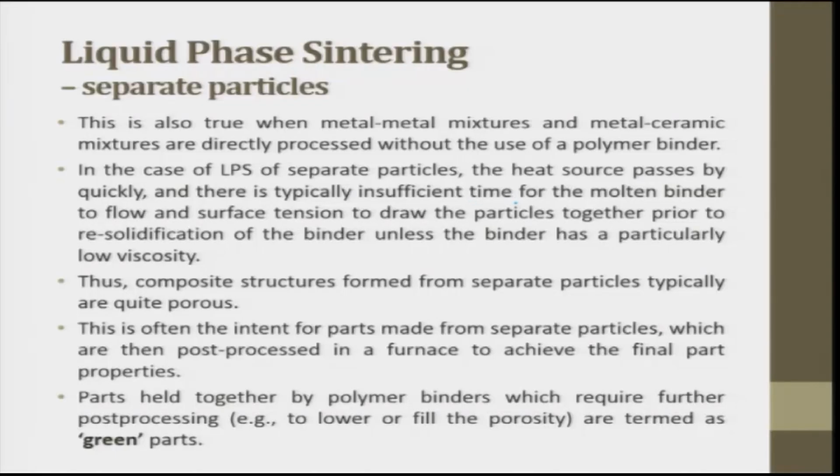typically insufficient time for the molten binder to flow and surface tension to draw the particles together prior to resolidification of the binder, unless the binder has a particularly low viscosity. Very, very important point. In the liquid phase sintering of separate particles, the heat source passes by quickly. Okay, there is typically insufficient time for the molten binder to flow, because it is very small in quantity.